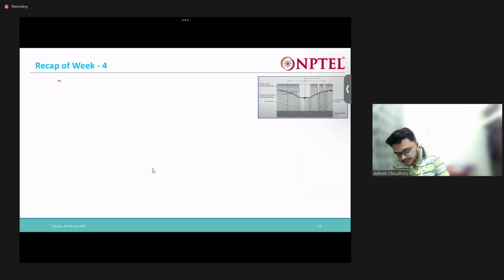So what we can write is that my small q is nothing but the flow at which water is being pumped out of the well, which is equal to k, the hydraulic conductivity, into dh by dr, times 2 pi r h. So k is my hydraulic conductivity, dh by dr is my hydraulic gradient, and 2 pi r h is nothing but the area, which area,